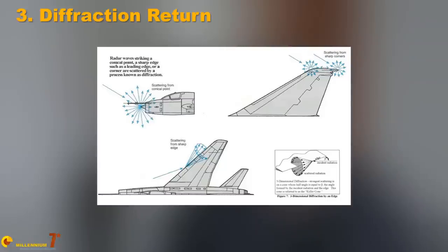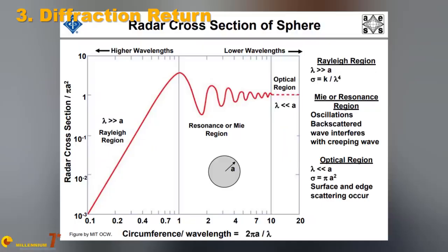Typically, the radiation is scattered in different directions. It may not be omnidirectional, but it is definitely scattered over a large solid angle, and that is definitely what you don't want if you want to preserve stealth. This type of scatter normally happens when the wavelength of the impinging radiation is of the same order of magnitude or up to an order of magnitude smaller than the local curvature. Smaller wavelengths have specular reflection. Higher wavelengths are either scattered or just not influenced.